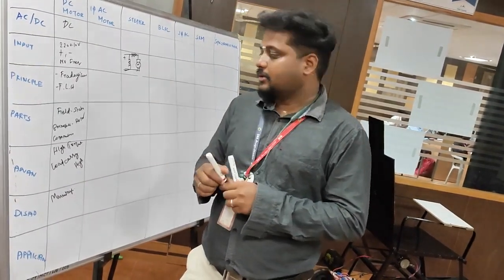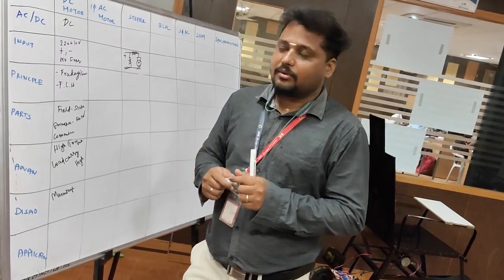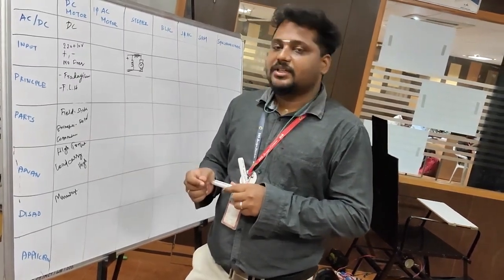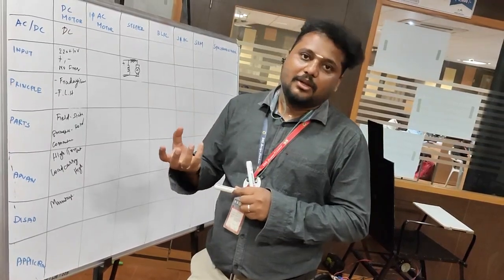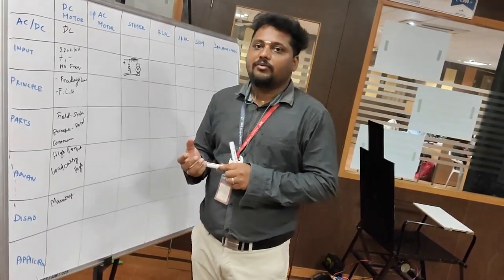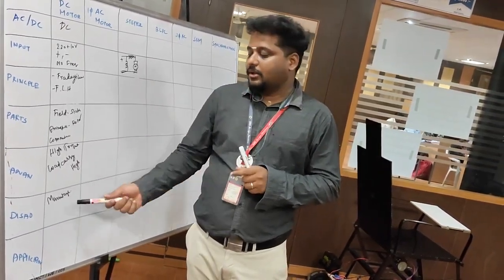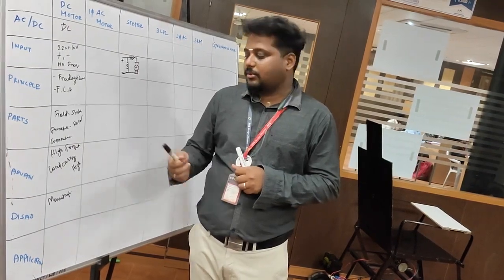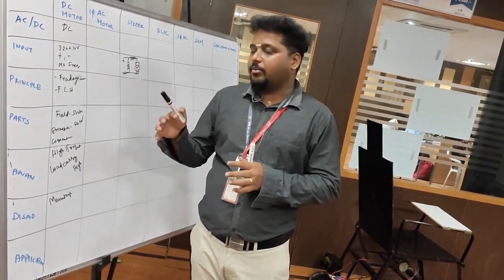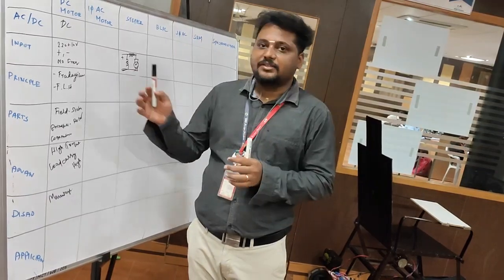Every 3 months we need to maintain the DC motor because the commutator and brush system burn due to heavy load carrying. So every 3 to 4 months we need to maintain the commutator system in DC motors.